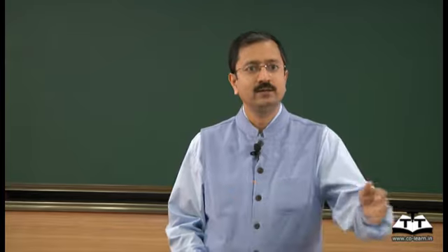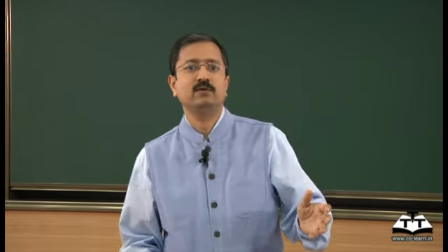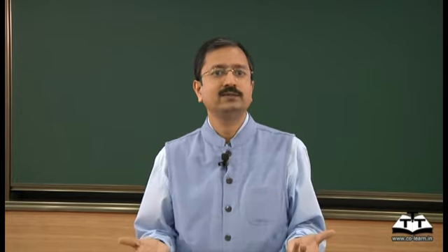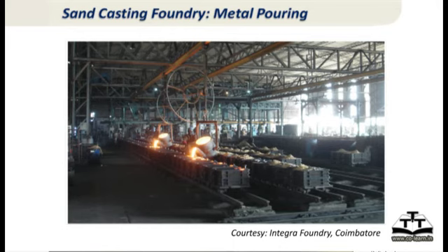And that variation is one of the many parameters in a foundry which are difficult to control. Obviously you cannot tap a ladle for every mold at the right temperature. You have to tap it in one shot and then pour it. So that variation is what leads to the inconsistent quality in castings, which is unavoidable. If you want castings at that cost, we have to accept some degree of variability of quality.